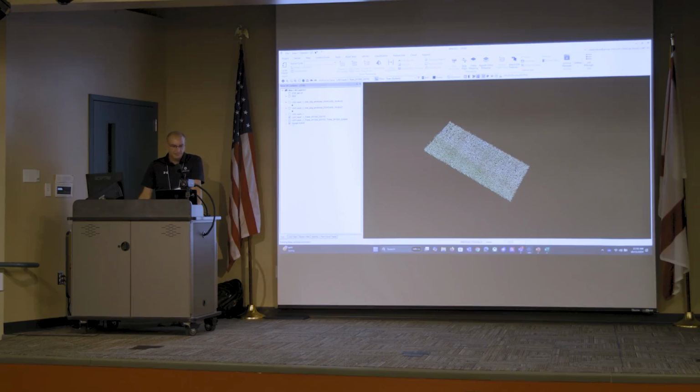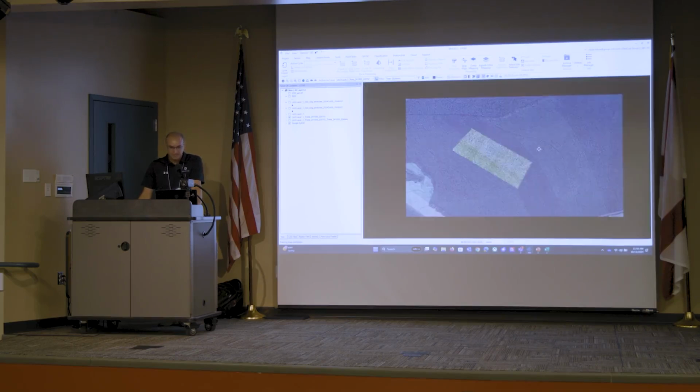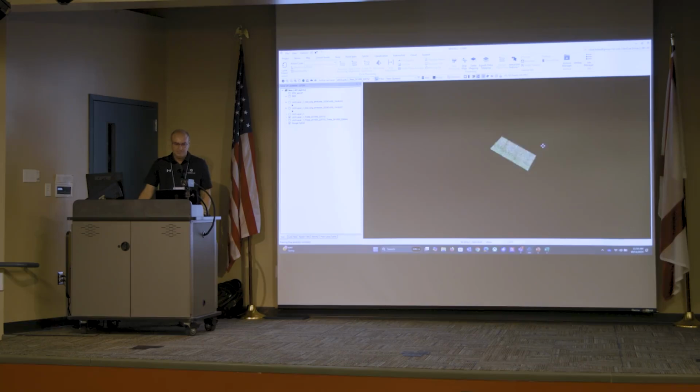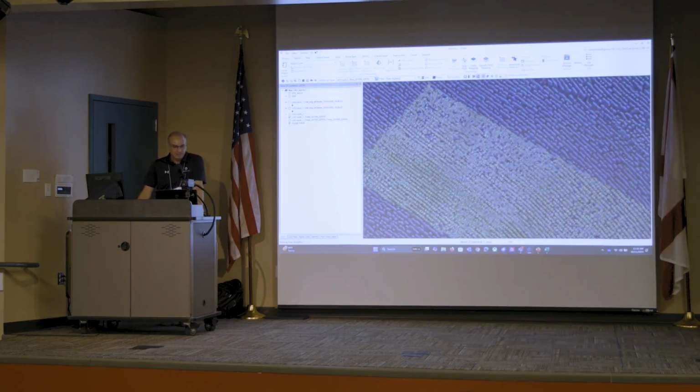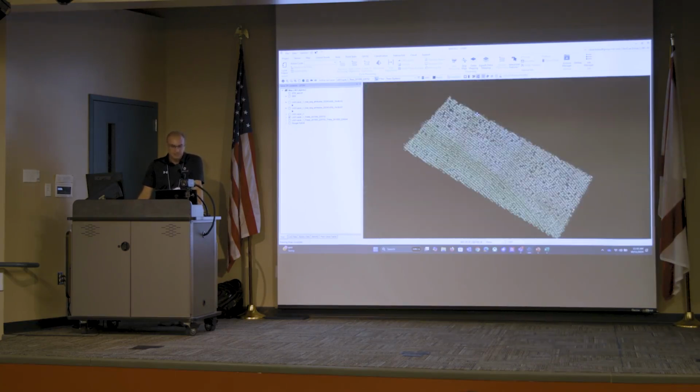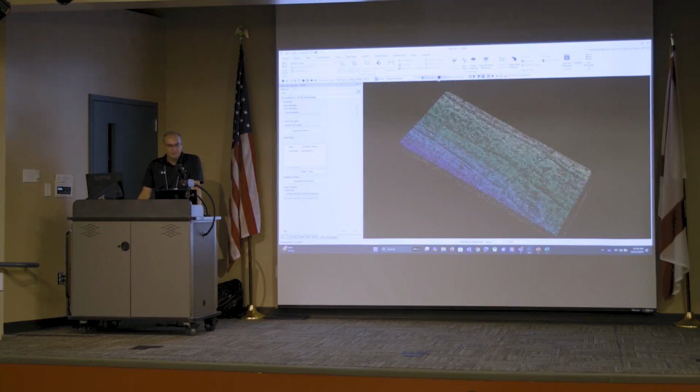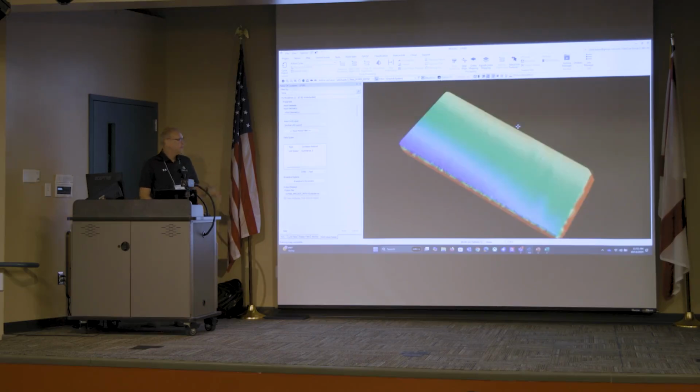Of course, it's a huge place. Let me see if I have internet connection. You can see that it's just a little part of the forest that they have on this spot, right? But the first thing that they do, as I mentioned, was the ground. So they basically use all the tools that we have here on LP360 for the ground. I think you have seen that, or if you are participating in the training, Kevin just showed, I think on the first day, how it works. So the first thing they do is to create this ground, then put here the elevation and thin surface. This is the first step that they're doing. This is basically used for the land preparation.